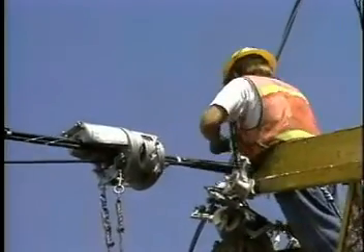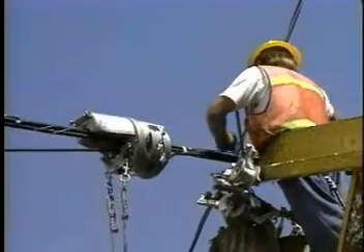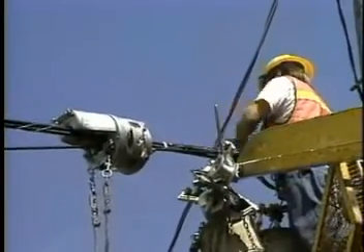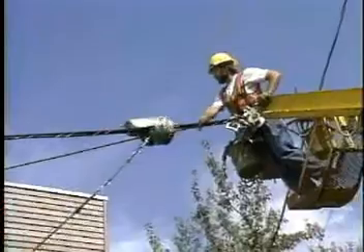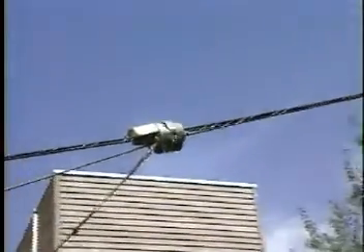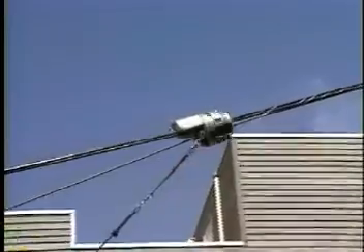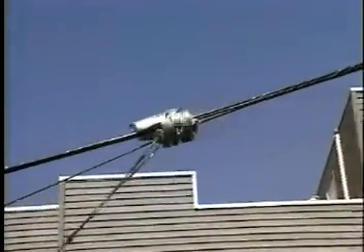The first end of the cable is clamped at a pole and to the messenger using conventional hardware. The lasher is attached, the lashing wire anchored, and the lasher pulled along. Fiber optic cable is fed from a reel positioned on a truck that moves ahead of the lasher.